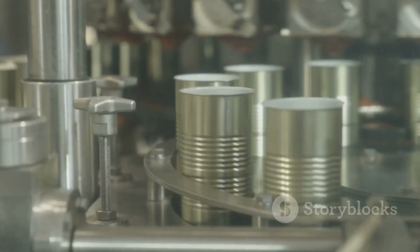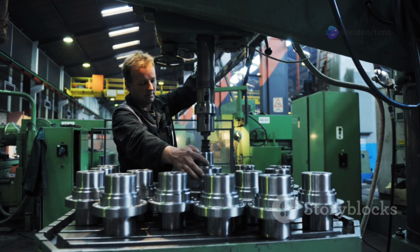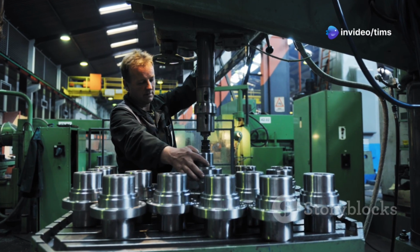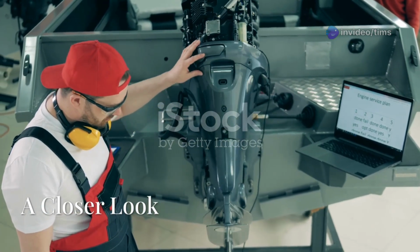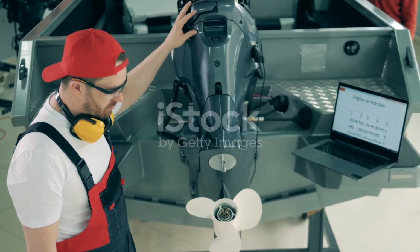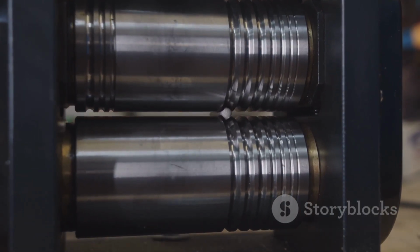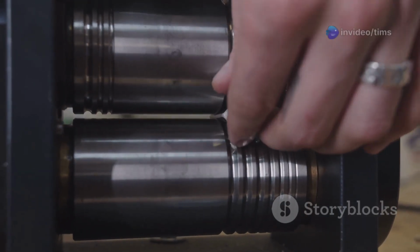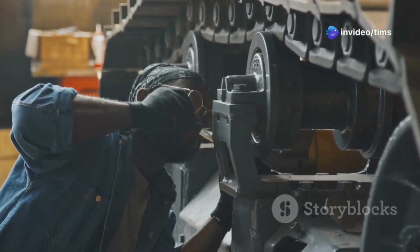These defects can occur at various stages of the manufacturing process. Identifying the root cause is essential for implementing effective solutions. Tooling issues are a common cause of curl defects. Worn-out dies or improperly set rollers can lead to inconsistent curl formation. Regular tool maintenance and timely replacement are essential for preventing these issues.